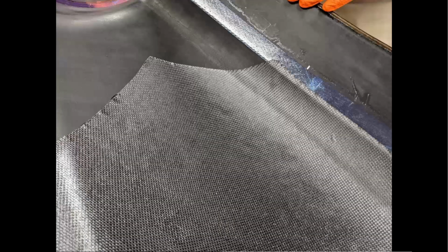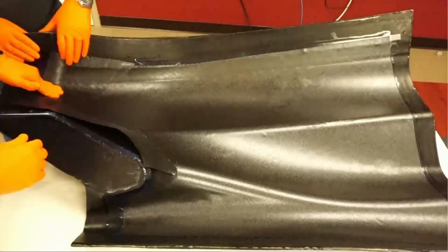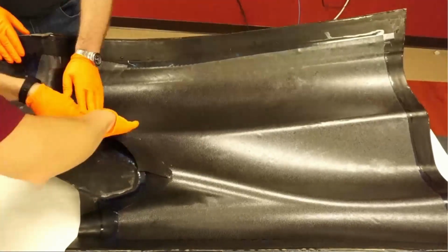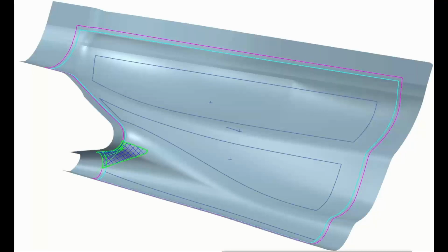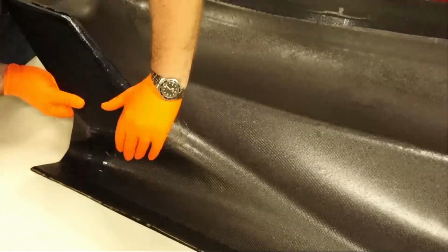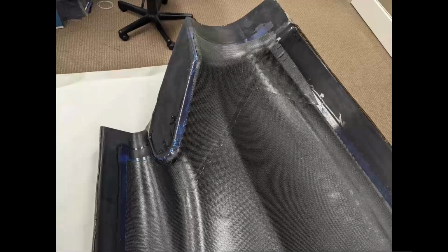When they go to lay the next one down, if they were using laser projection, probably a little more accurate, but there should be a half-inch overlap here. There's 2 areas. You can see that in yellow. Those are the 2 areas that probably require the most work to smooth it in. But they were able to put that in relatively accurately as well. And then there's one smaller piece on the inside where we have that very compound curvature. You can't have one ply absorb all that deformation. At least this prepreg wouldn't do it. And so there's the part laid out that you just saw in Fibersim. Those plies went directly to SDA as DXF files, and they went ahead and cut them and laid them up for us.